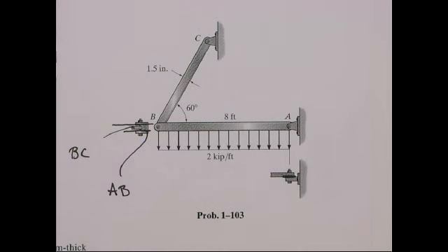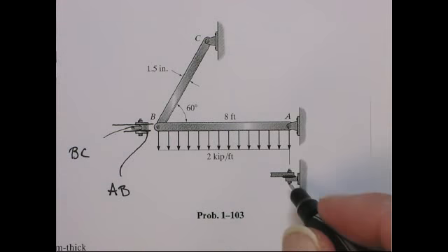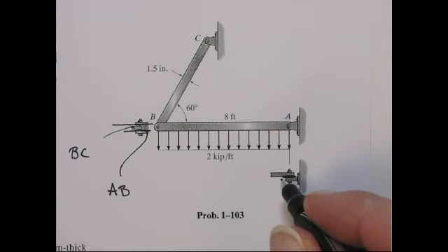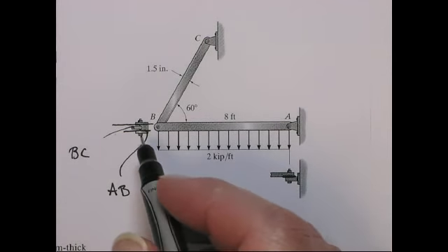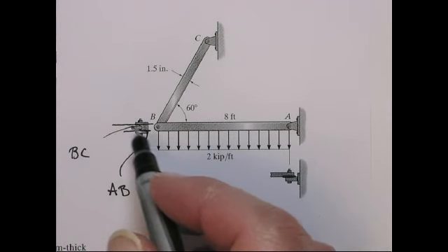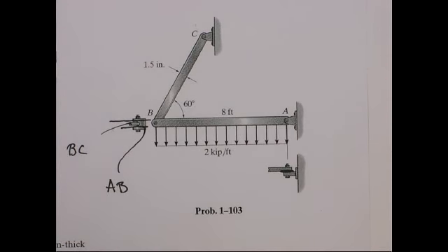So I want to talk a little bit about the shear and the pins. Again, we'll see the difference here. Pin A has one shearing plane, so it's what's called single shear. And then you look at the pin at B, it shears along two planes. So let's first look at A. A is a little simpler, and then you'll see how the double shear case is able to do a better job of sustaining the shear loading than the single shear case.